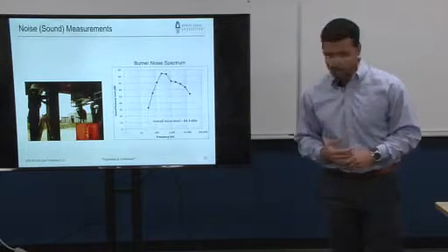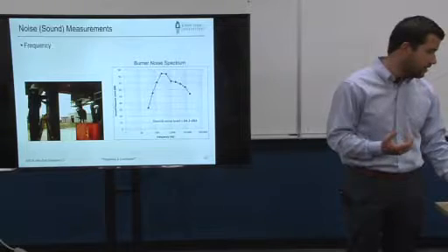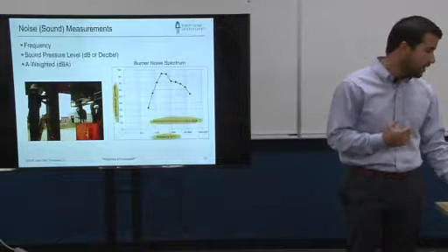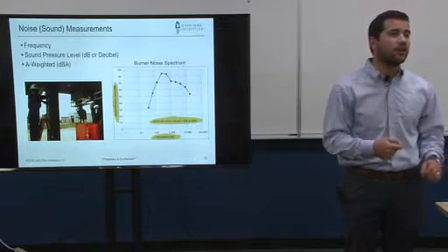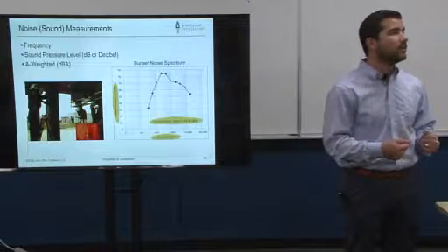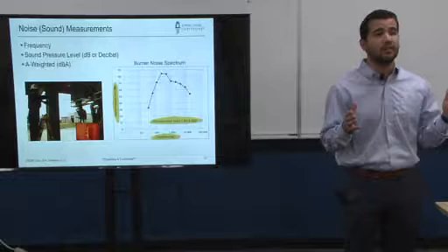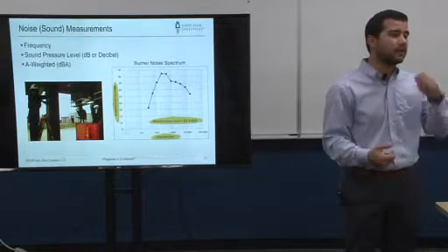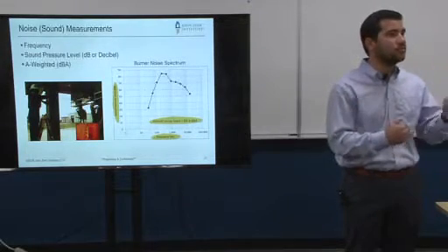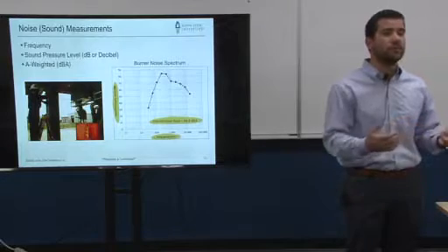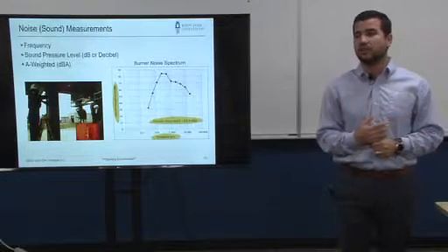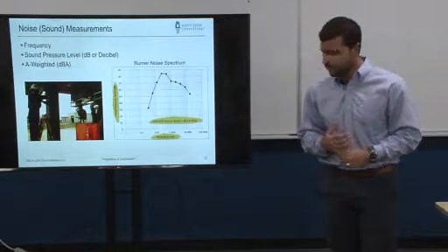Really the way to measure it is you just have a noise meter, and you have to have an understanding of where the operator is going to be located. So typically it's measured about 3 foot away from the burner inlet. And again, this is set up by API. API tries to regulate this, or whatever pollution regulating body you're applying yourself to.